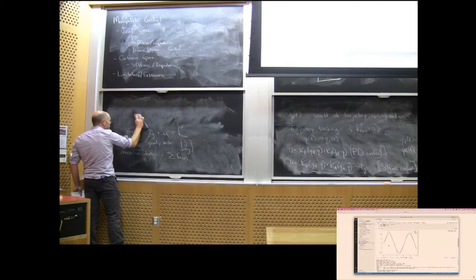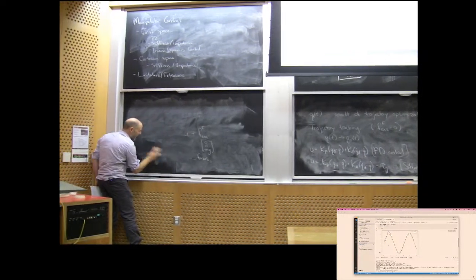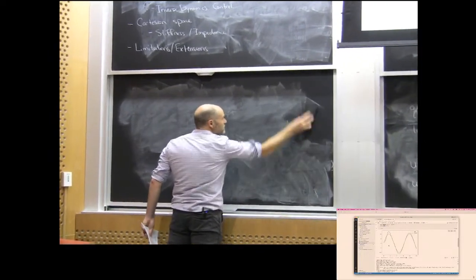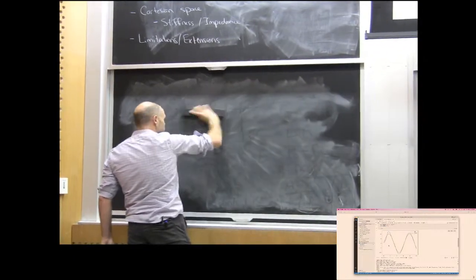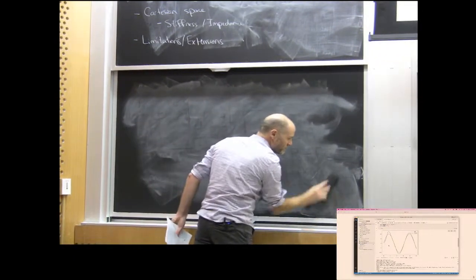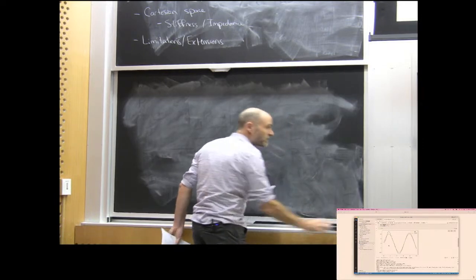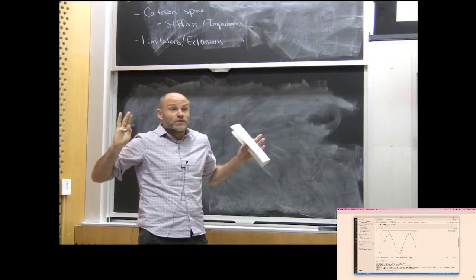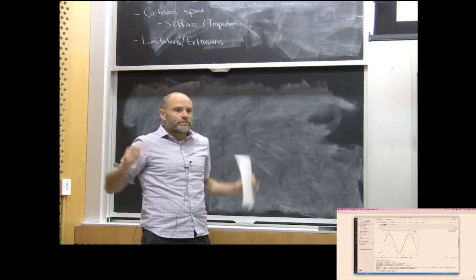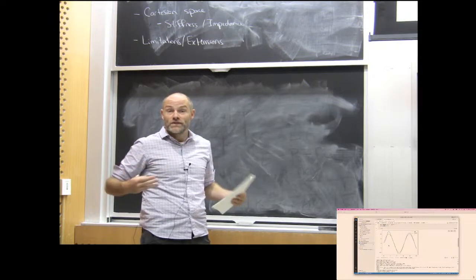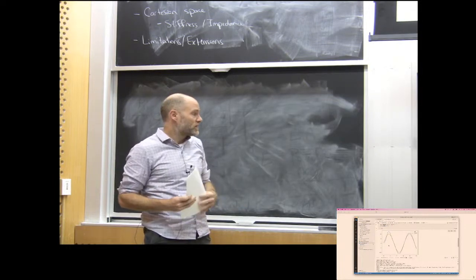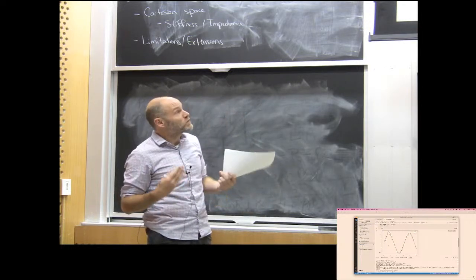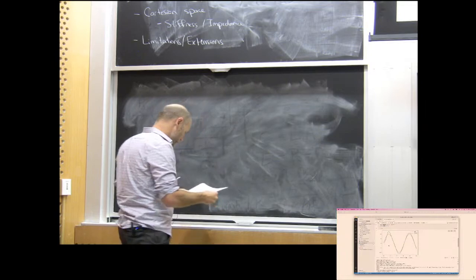What would you do to try to get around that lag, if you will, which is, there's an extra piece of information that we haven't given our tracking controller. Which is we know arbitrary derivatives of Q desired. If we tell it where it's going to go and give a feed forward term that uses Q double dot, then we can do even better, we can get better tracking performance still. Okay?